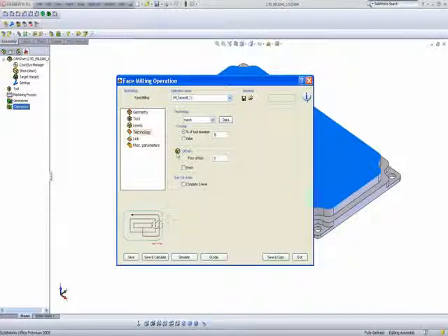My next option, I have offset. How much do I want to leave off the floor? I can say I want to leave, let's say, 0.2 millimeters off the floor. And if I want, I can go back and say, after leaving 0.2 millimeters off the floor, I also want to do a finish cut. Let's simply do now save and calculate.